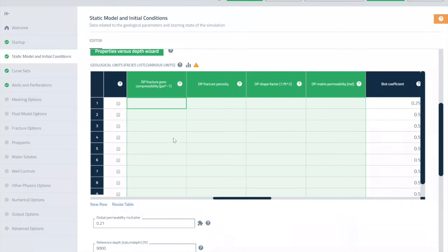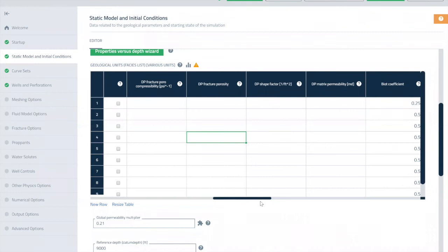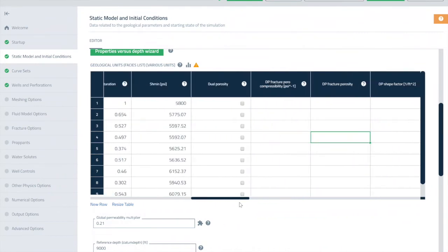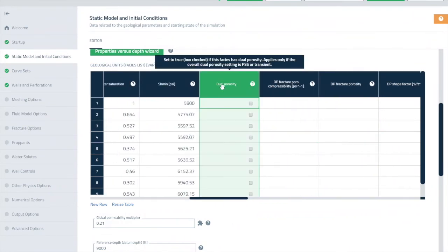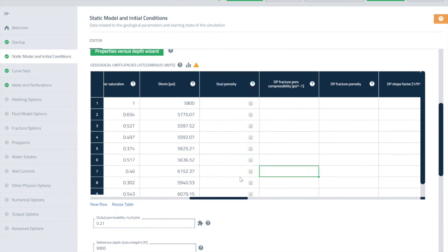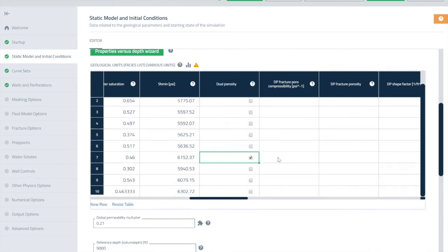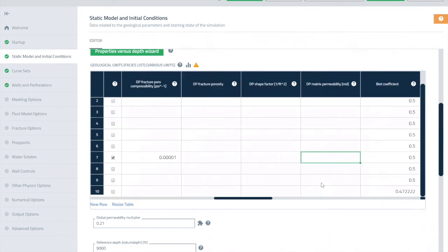The reason that's important is because if we go to this topic of leak off, the fluid leaks off into the quote fracture elements surrounding the hydraulic fractures. They have much, much lower pore volume than the matrix does, right? And so the question was asking, well, it seems like there's a mesh dependence, because the amount of fluid that leaks off, the average fluid pressure of the matrix element, will depend on its size. It's an exactly correct point.